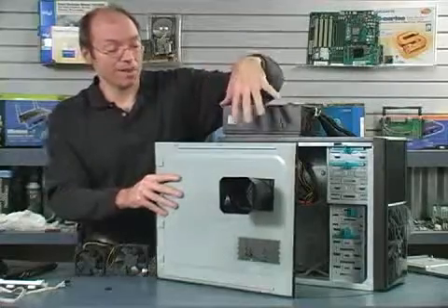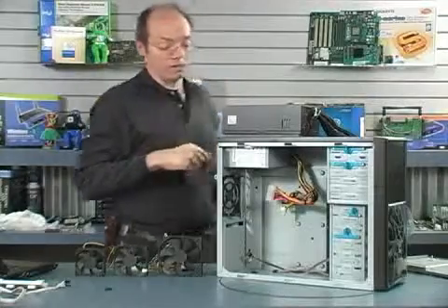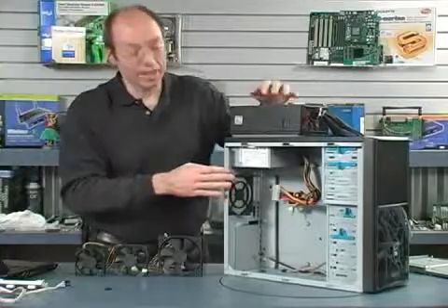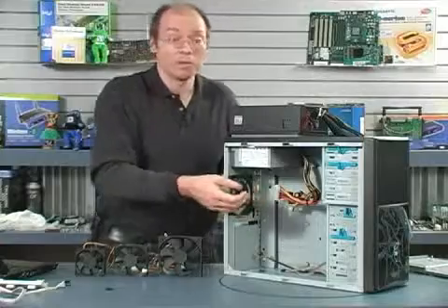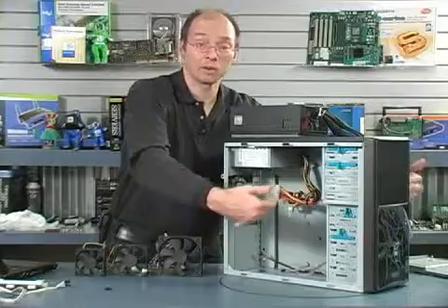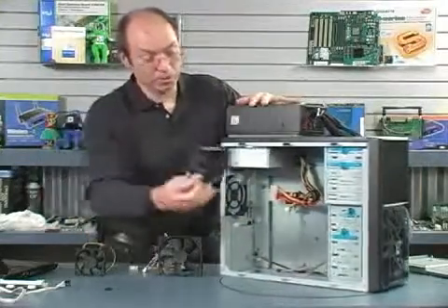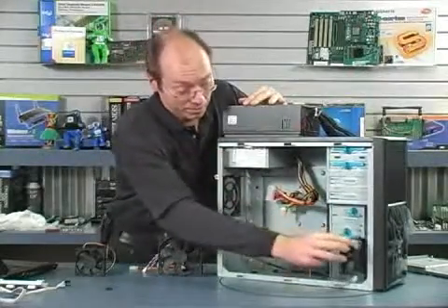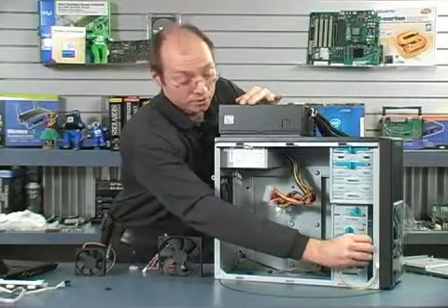See, the idea is that the air inside the case is heated up. So in order to better cool the processor, we want to draw air directly from the outside to cool the processor. So again, that's why we want more air generally coming out than being blown in, because we want to create a suction. We want to create a vacuum so that air is being taken in through the various vents on the system. So again, what we can do in this, if I'm going to mount 4 or more hard drives, I'll usually take a 92 millimeter fan and mount it up in the front here so that it'll adequately cool all of those hard drives.